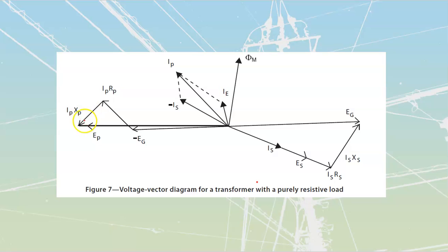These are my main transformers that we're going to look at. They're poorly drawn inside of a bunch of these, so even though they went vector crazy, they got sloppy and did not draw them properly. But there's a little triangle over here, and I want you to imagine as if it's got a hinge. It is always going to be attached to this because I'm going to have my primary value of voltage, but I'm only going to get a certain amount of counter EMF because I've got some drops inside of there. Same with this side over here.